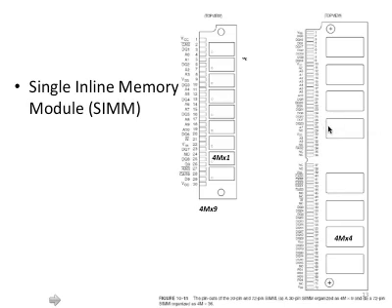And on the right side, this is another design where we have a slightly different organization. We use a different DRAM chip, and each of them here is 4-bit. So together we have a 32-bit data bus for this chip. So you see the 9th is used to do error checking? Yeah. The 9th is used as error checking. 22 divided by 11 because of the multiplexer.